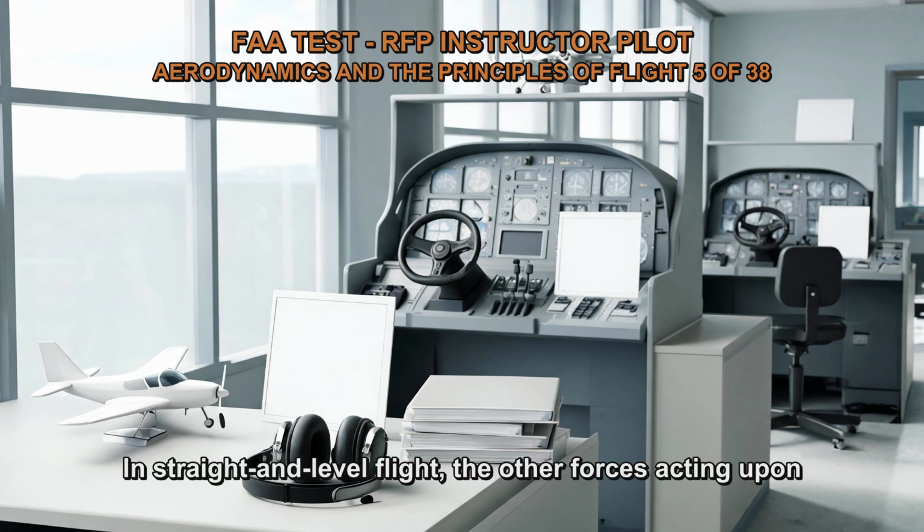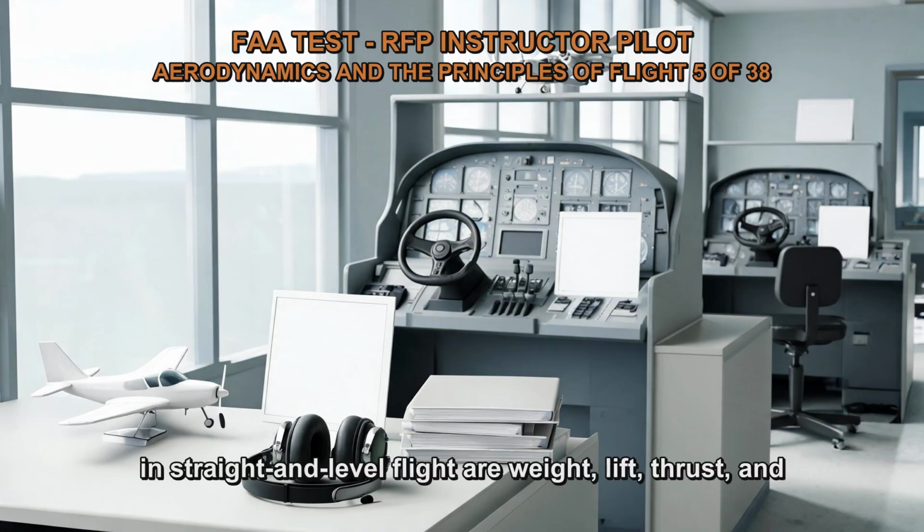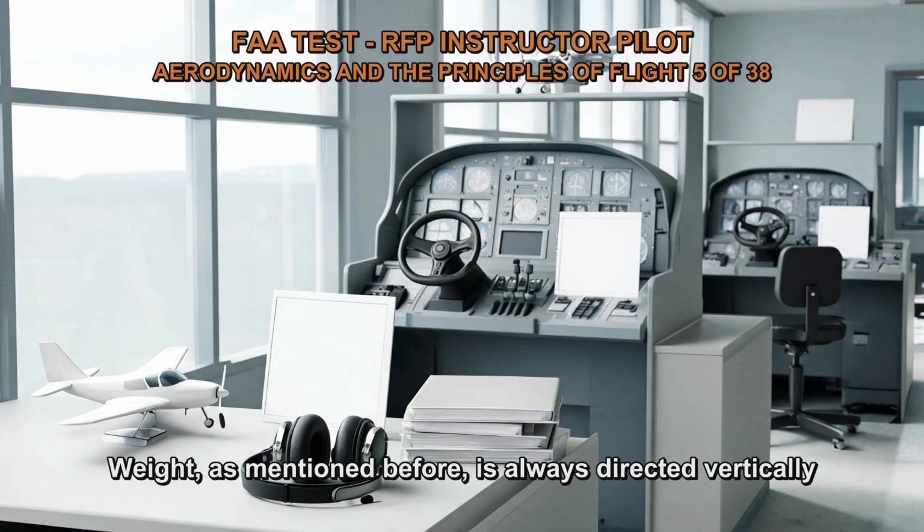In straight and level flight, the other forces acting upon the airplane are balanced so that the net force is zero, allowing the airplane to maintain a constant altitude and airspeed. The four main forces acting on an airplane in straight and level flight are weight, lift, thrust, and drag. Weight, as mentioned before, is always directed vertically downward.